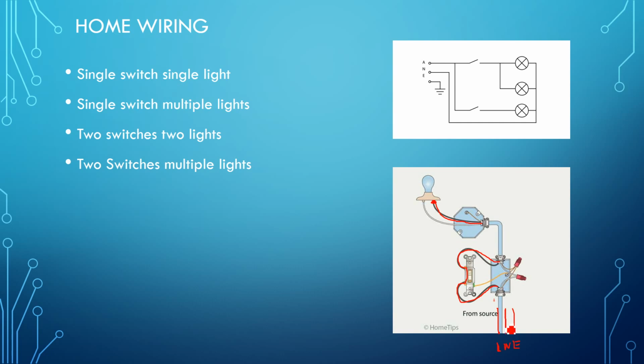Then we have the neutral. What will happen to the neutral? The neutral here will go directly to the other terminal of the light. So neutral is coming here, as here we have a splice. This one is called a wire nut connector. It is connected here because we will have the cable till here, and then after that we will have the wire. So here is the connection, and then the white one goes directly to the neutral line. All right, after that we have the earthing. So what is the earthing for?